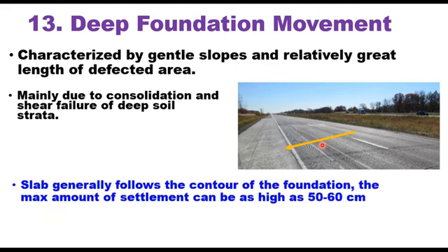The slab generally follows the contour of the foundation, and in extreme conditions, the maximum amount of settlement can be as high as 50 to 60 centimeters. And the only solution to this problem is to repair the soil subgrade.